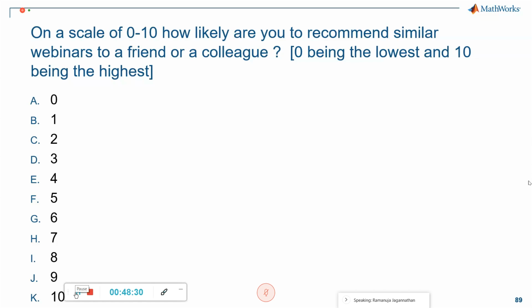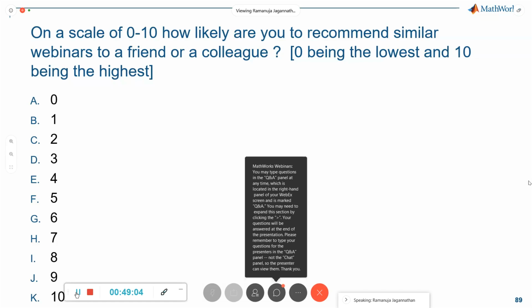Another question asks how we cater for the changes in battery parameters over time, so how to make sure the battery model is working accurately for the changes over time. One thing these battery models have, what I showed today, is also the state of health. So basically, you could parameterize these batteries, and how the health would degrade over the usage. In the particular blocks we showed today, you could use that to model the battery health degradation.